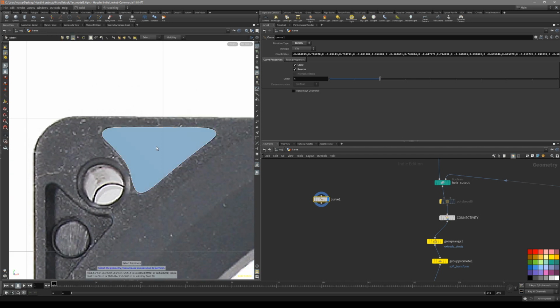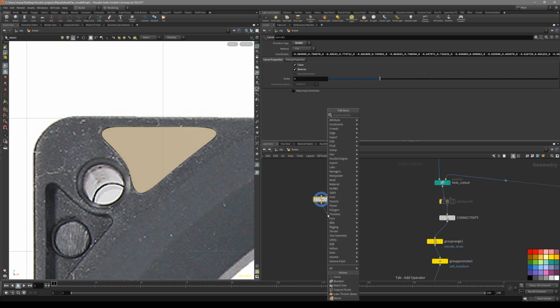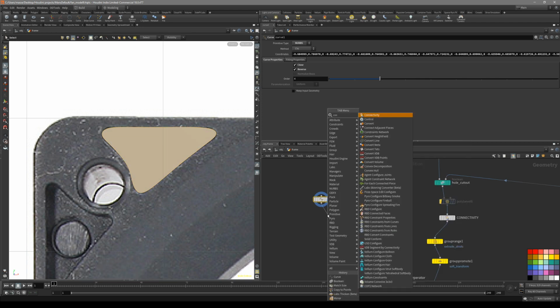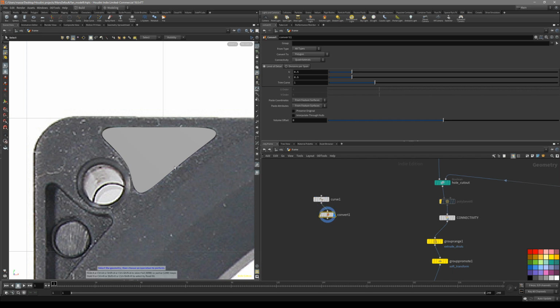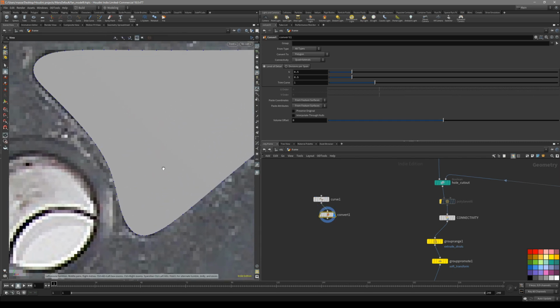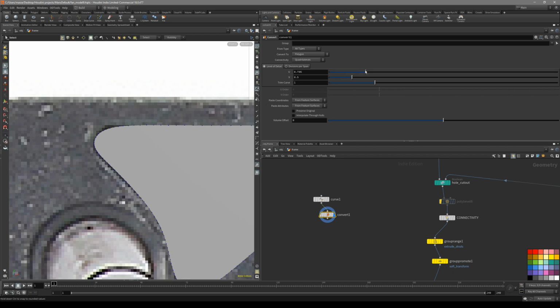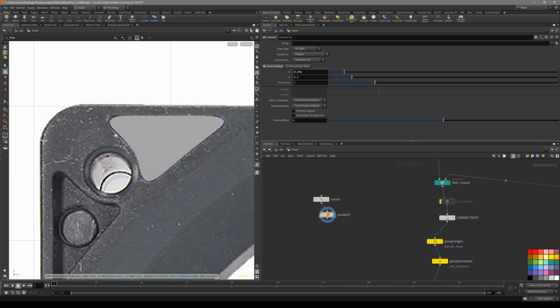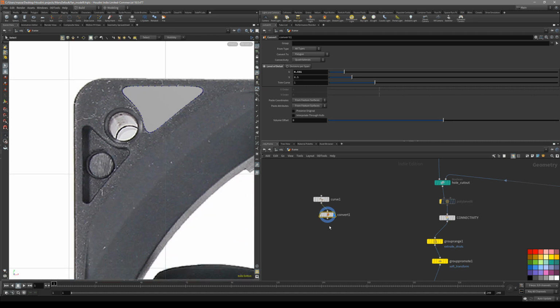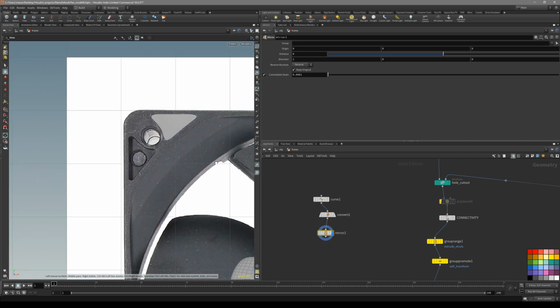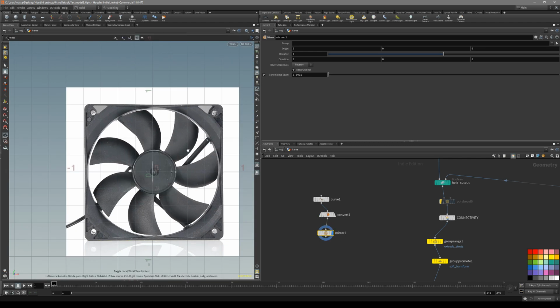One thing to note is that these are not polygons right now. What we do is convert. You can see how dense the geometry is right now, but we can make it a little bit less dense with this U slider, so something like this. And now all we need to do is mirror it. Press enter, take a look where the mirror happens.